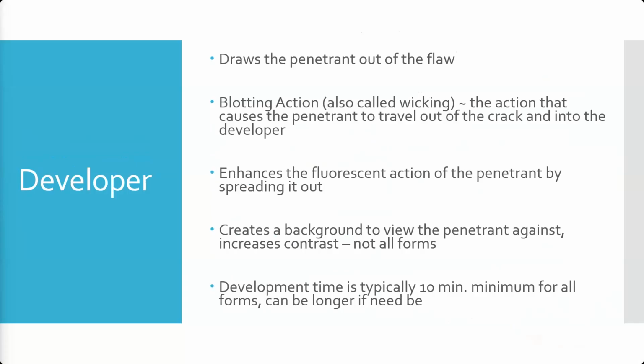Okay. With most developers, we're looking at a minimum of 10 minutes that we need to put it on and allow it to sit and blot, or wick, that dye back out of the flaws. Minimum of 10. Sometimes it needs to go a little bit longer, right? Sometimes it takes a little bit longer to bring that dye back up to the surface. There really isn't a concern from an inspection standpoint of leaving it on too long. It just means it's going to pull that much more dye to the surface. There is a concern with leaving it on too long, though, which is that you don't want it to dry and harden. I'm talking about leaving it on for hours or days after your inspection.